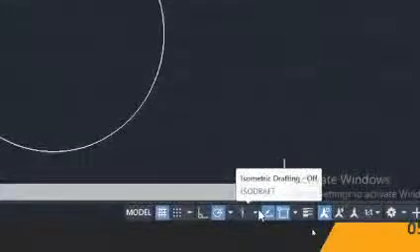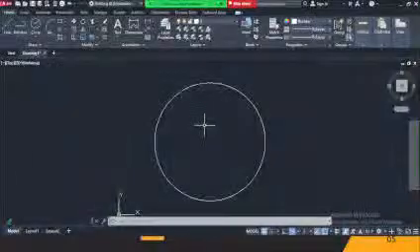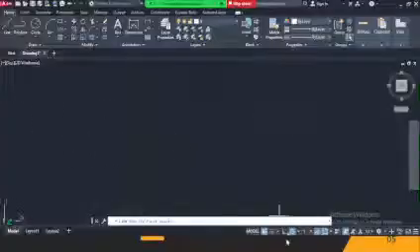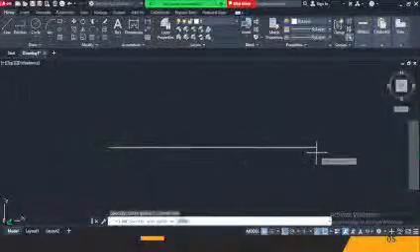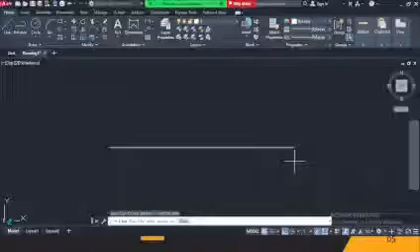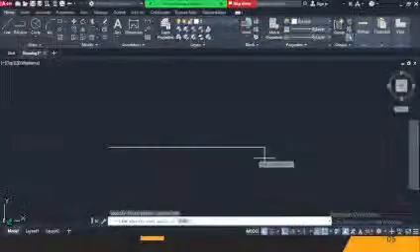Sometimes some persons say AutoCAD restricts your cursor at an angle 0. Whichever one, you are still correct. It's either you are going straight, upwards, or sideways. You can't use auto at an inclined angle. So if I click the line tool and my auto is on, I can either move this way, that's the horizontal plane, or I move up. So at any point, it might be at angle 0 or at angle 90. These are the two ways I can move.